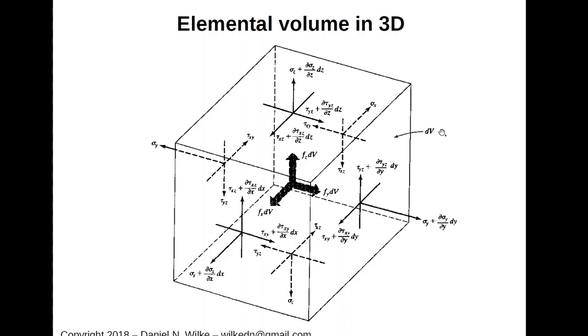That is that volume. And if I look at the back face of the structure, I'd say that on the normal component, there could be a stress component acting normal to that surface. There could be stress components acting in the plane there. So this is a much more general version of stress that could act on that plane. So we have three components that could represent some kind of traction on that surface. Okay, so that's that stress component. There are the two shear components.